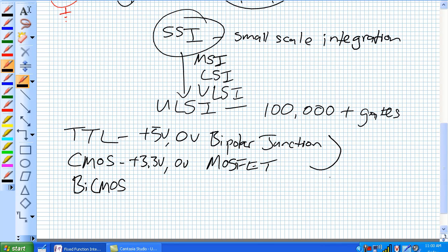It just happens that they're using different voltage levels for the same logic device. Their AND gates and OR gates, even though they're implemented with contactors, are very similar to the logic that we're discussing here. So Allen Bradley PLCs use plus 24 volts as a high. I also believe that Bachmann PLCs use 24 volts for their logical high.